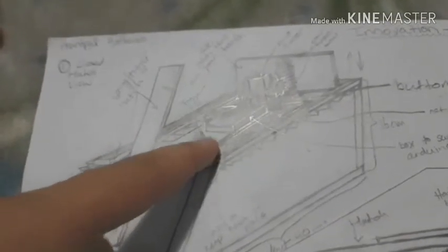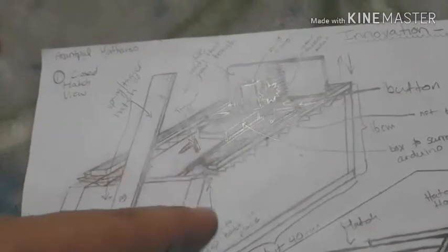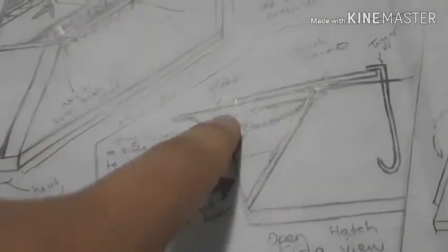So basically how this sketch works is by a spring and this little trigger over here. The way this sketch would have worked is that I would have pushed this handle all the way down and hooked it inside this trigger. Then once the mouse comes inside, the bait would have been attached on the bottom side of this trigger. Once the mouse touched it, this hatch would have moved and gone up, resulting in the hatch closing. The hatch was going to have a spring attached to it, and the other end of the string was going to be attached to the wall.